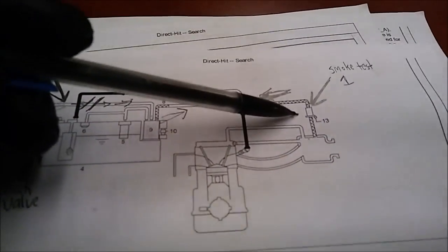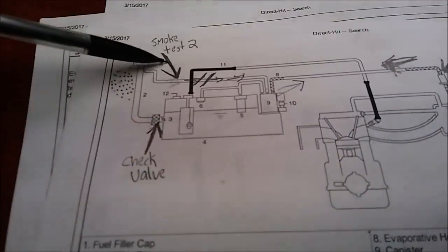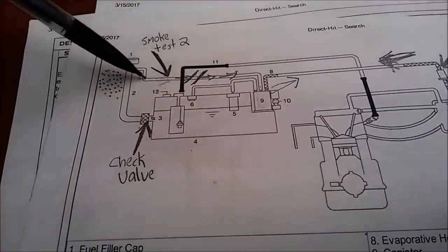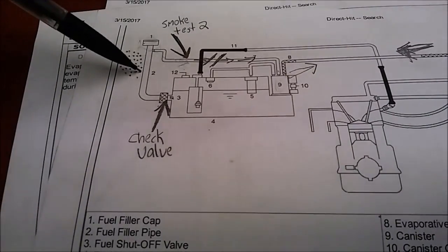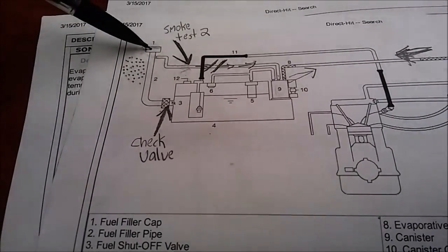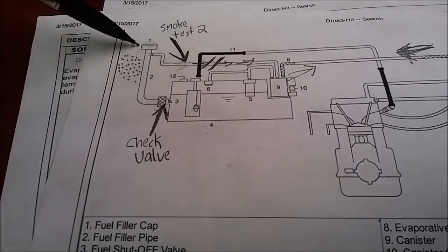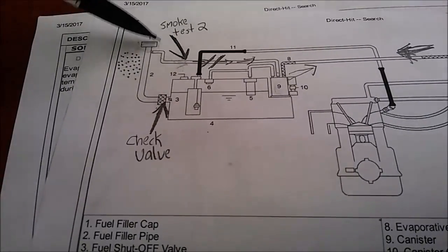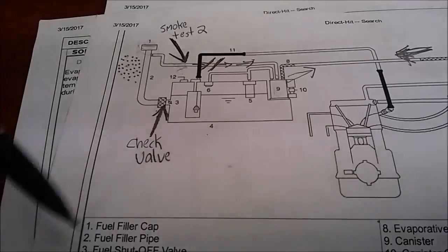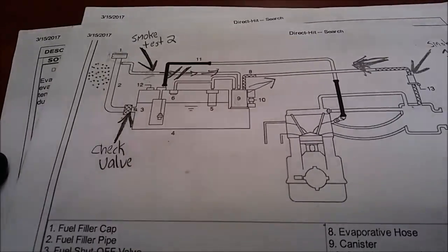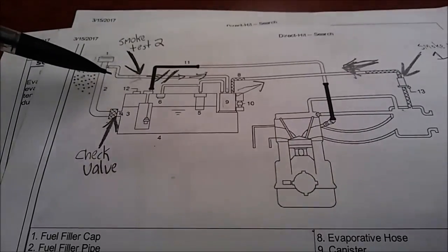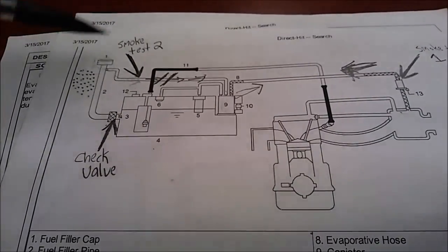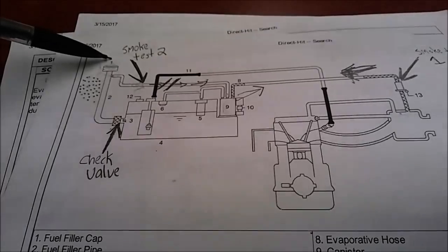We started over here at the purge solenoid, and the second place we did was this. We would need to hook up directly to that metal pipe going to the filler neck to smoke test that and the fuel cap properly. Or we would need to use some sort of a fuel cap adapter and do all of our smoke tests from there. I was basing the fact that we didn't have a fully smoked EVAP system off the fact that I didn't have smoke coming out of this.